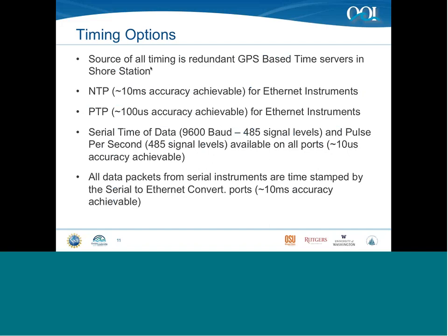So timing signals, there's a number of ways to make sure that each deployed instrument has a sense of accurate time. All timing is based on shore-based GPS systems from the shore station in Pacific City, Oregon. We can support NTP or precision time protocols, or PTPs, for Ethernet instruments.